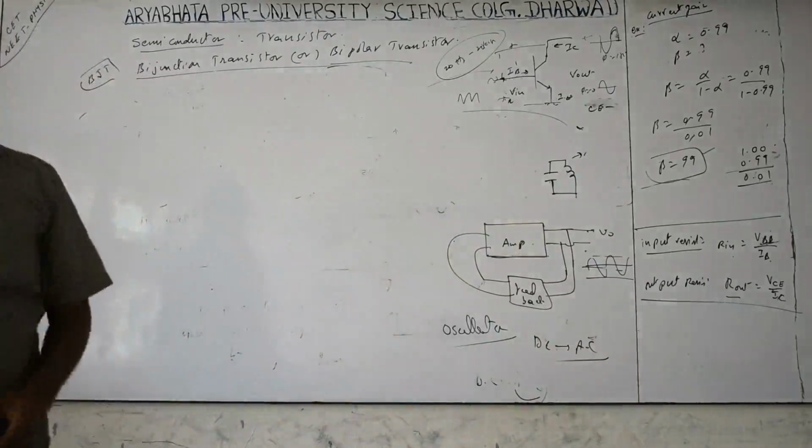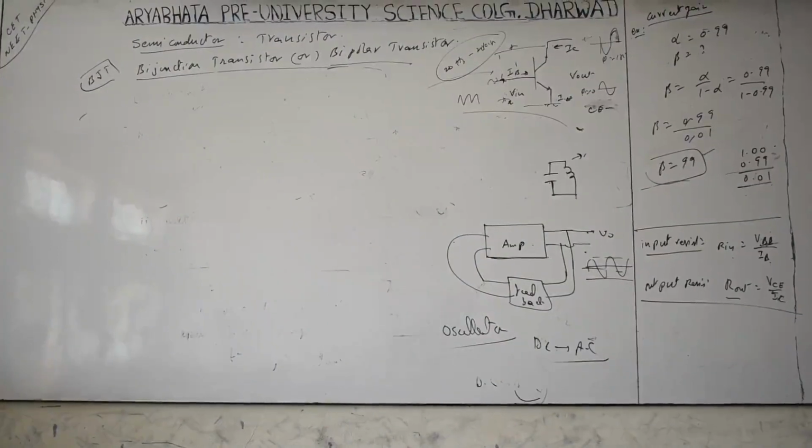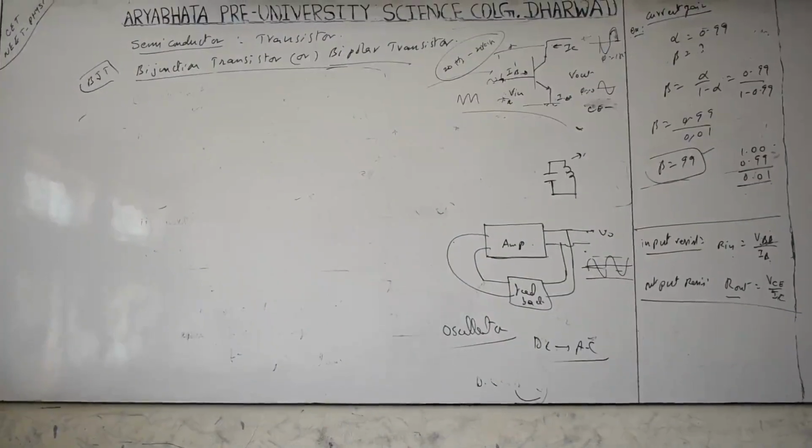And as the IC current decreases and increases, this takes place continuously. The amplifier amplifies the small signal coming into a bigger one, and power is continuously supplied to this LC oscillator circuit so that it continuously oscillates. Without the amplifier it cannot oscillate for a long time. So this is called a feedback circuit.